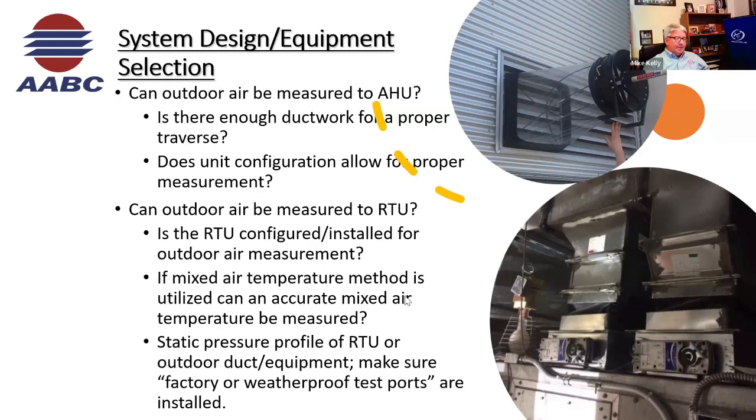If the mixed air temperature method is utilized, can an accurate mixed air temperature be measured? That happens a lot, and I say yes, there is a way. It's time consuming and tedious, but it is an accurate way to get airflows. There's an art to it. You have to understand where temperatures should and shouldn't be taken. Stratification is always an issue.